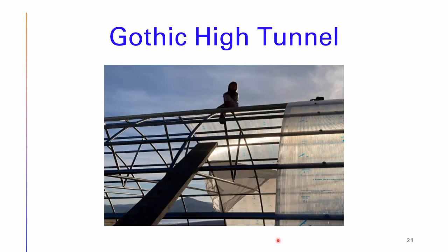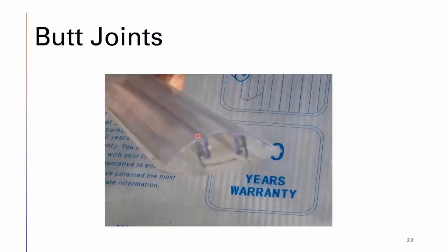And then you put butt joints. I use 2-part butt joints. That's this stuff. Not a very good photo. If you're looking around on the internet, a lot of places will show you H-channel. That's a 1-piece butt joint. I don't like H-channel at all. I highly recommend you do not buy or use H-channel butt joints.